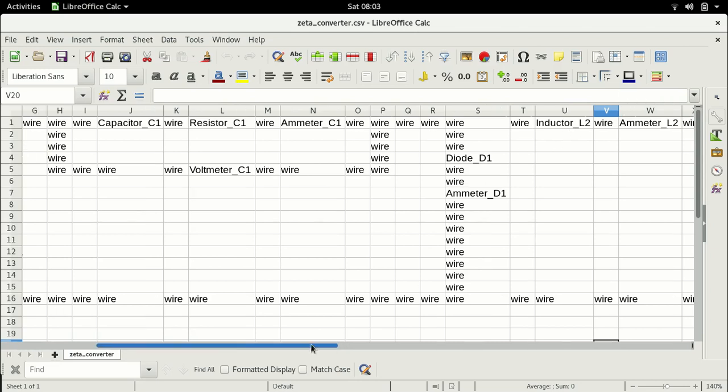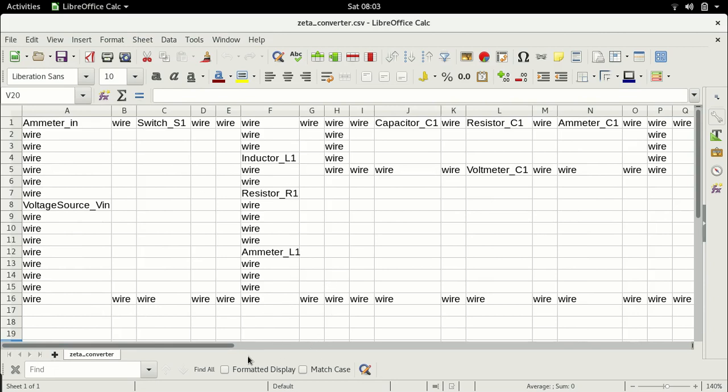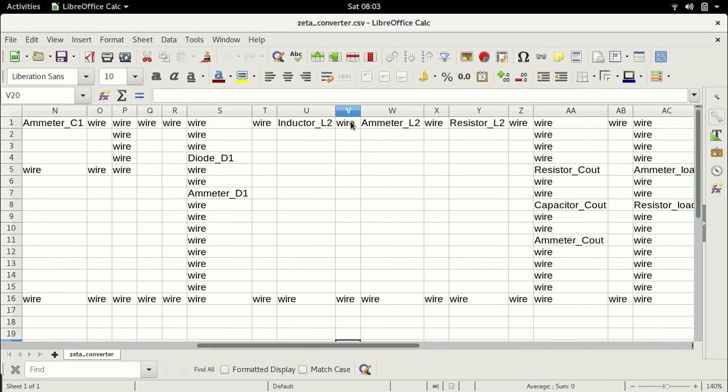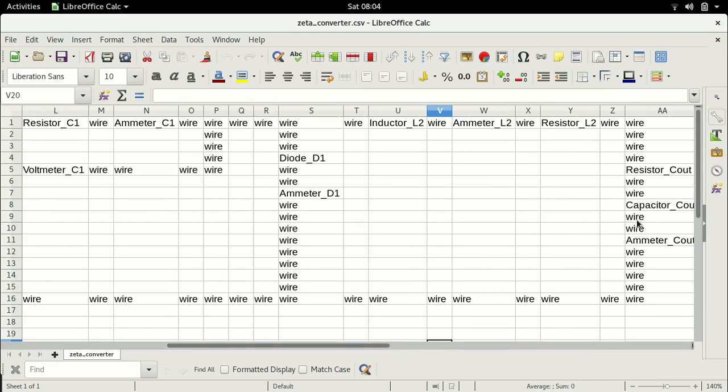Now, as the current through both of them starts increasing, the capacitors also get charged, because as this current increases, the current through the capacitor increases, which means this capacitor is getting charged. And as the current through the inductor increases, the current is also going to flow through the capacitor. So the output capacitor is also going to get charged. So now these two capacitors are getting charged. And as you can notice, the current through them is the same, which means the voltage across these two capacitors is the same, right?